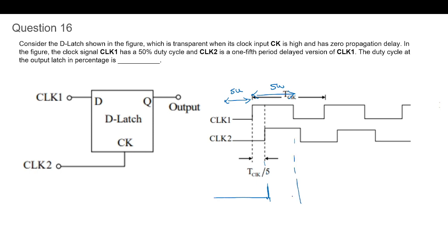So here also it is positive, so it will transfer till this much. So we have to find the duty cycle for this circuit. Now this is off for 5 plus 1, 6 units of time, and this is the point. So this is again 1 unit, this is also 1 unit because of the clock. So this is 3 units. So this duration is 3 units, right?